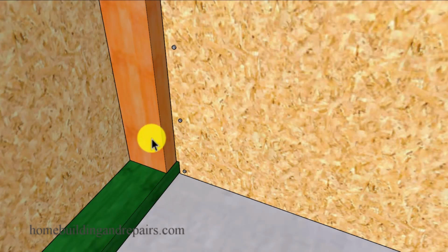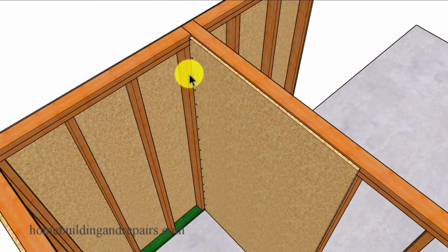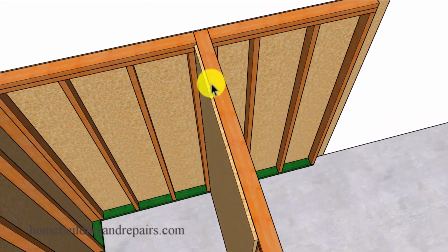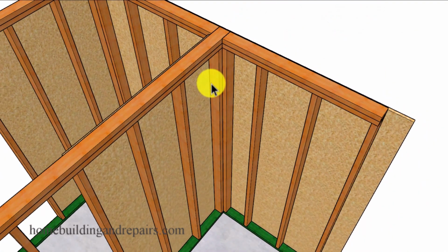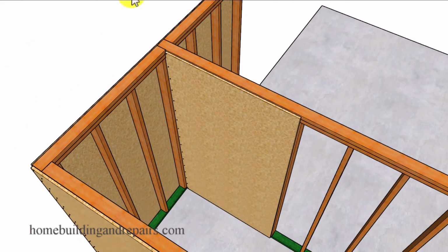And you could always nail the heck out of this framing stud into the 4x4 and then put some additional nails through the shear panel on the other side if you're looking for a little more structural strength. But we're going to need something here for drywall backing. And of course, this is the main reason why most builders miss this. They frame the walls and then butt the shear panel up against the framing stud or the wall here. They don't let it run through, and it's not that difficult to do. And believe it or not, this is something I started doing years ago. I don't know when or if I ever came across a detail that required it.